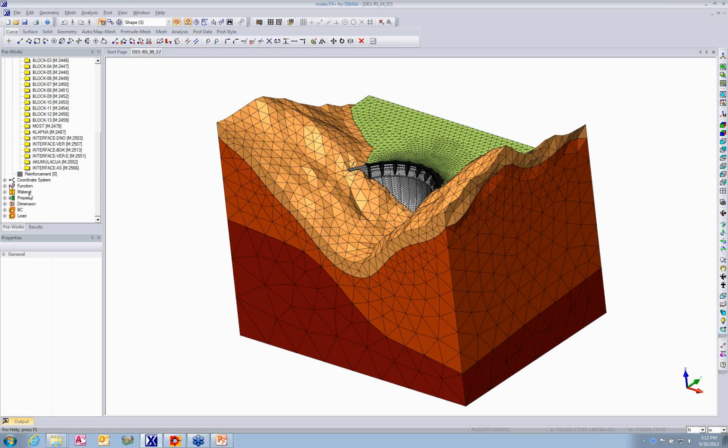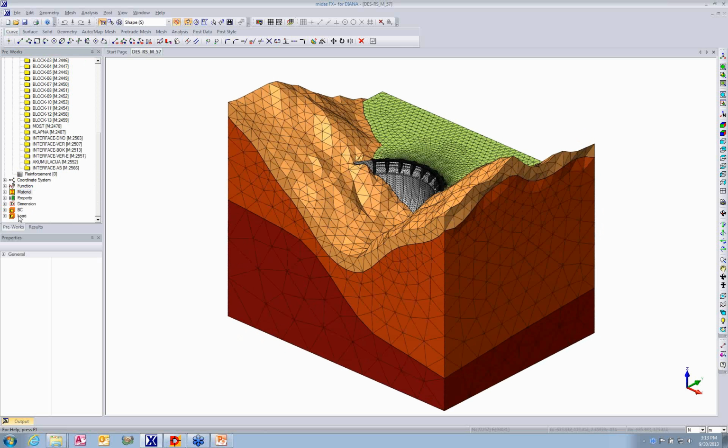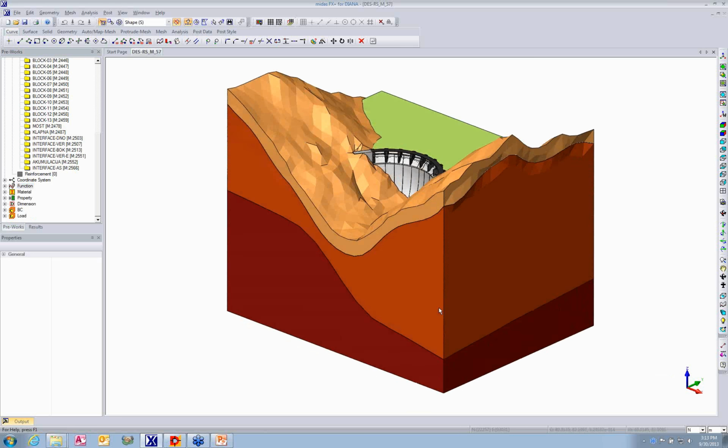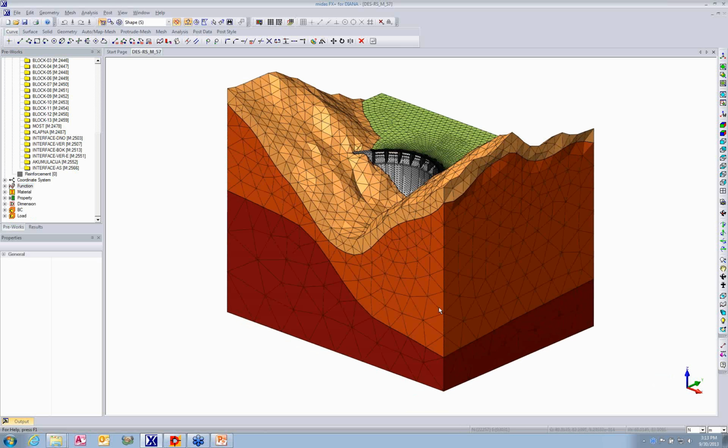Moreover, here you can deal with some basic material properties, or you can proceed with defining your loads and boundary conditions. And if you are dealing with some sort of variation, depending on time or geometry, you can assign the corresponding function to those loads and boundary conditions. The next step after having your model mesh in FXT is transferring that to the new environment, Mesh Edit. You easily transfer it through the analysis and edit model with Diana Mesh Editor.